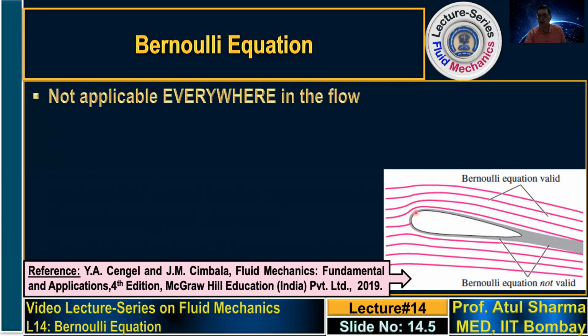So above the aerofoil you have a boundary layer, and on the back side you have a separated region which is called wake. So in this separated region and inside this boundary layer, the velocity gradients are large. Note that this aerofoil is stationary and the fluid has a certain velocity. So when it passes over the surface of the stationary aerofoil, there is a velocity gradient which sets in, because at the solid surface you have a no-slip boundary condition. So inside the boundary layer, the velocity gradients are large, and whichever fluid you consider, it has certain viscosity, due to which there will be viscous resistance.